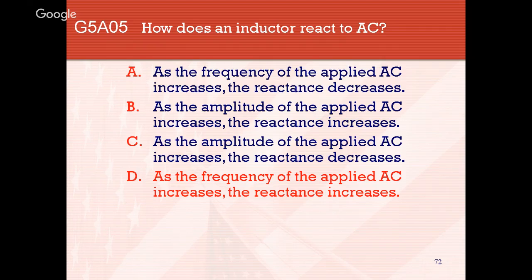It doesn't decrease. In a capacitor, as the frequency increases, the reactance decreases. In an inductor, as the frequency increases, the reactance increases. So there you go.